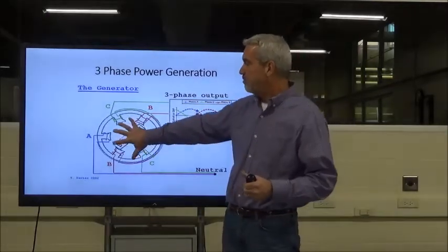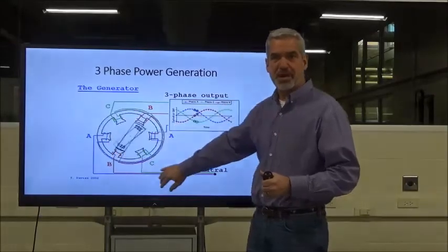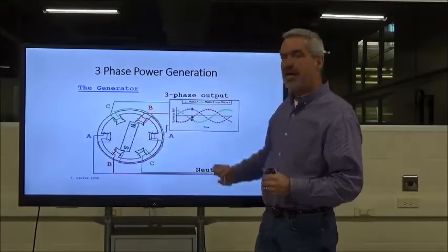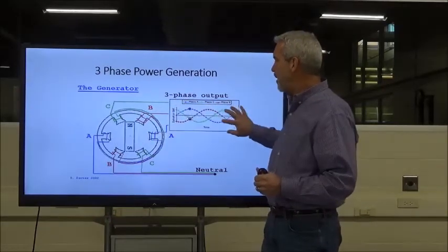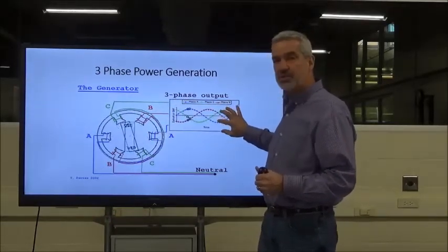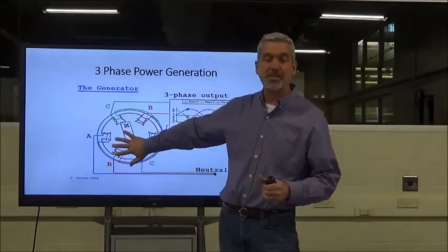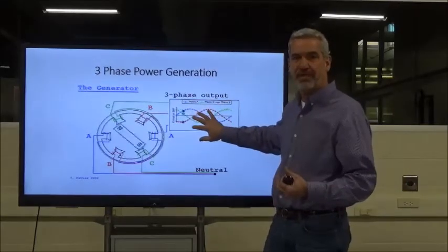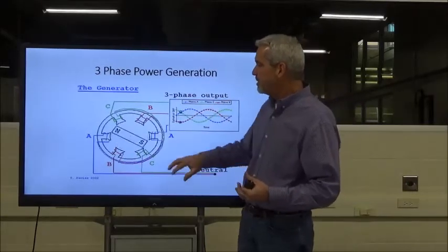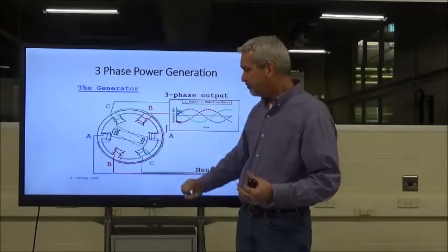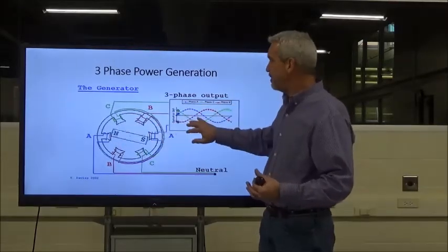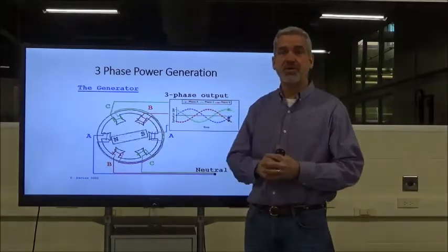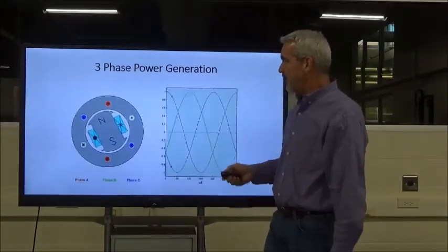So we can consider this the Big Rivers power plant or Paradise, whatever you want to call it, and they're generating it. We've got 3 lines coming down from the transmission lines, and we'll connect this to our motor. Now, it's coming out of our power plants at a much higher voltage. We'll have to step it down to probably 480 volts for our motor. But my point is that this is where it's being generated and how each of the 3 phases is being generated. And of course, we connect these 3 phases to our motor, and you've got a 3-phase motor system right there. Again, it's another example.